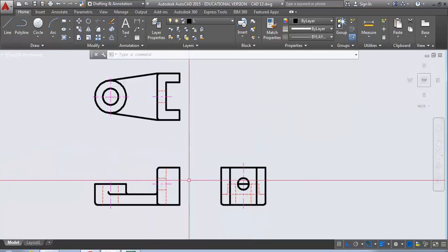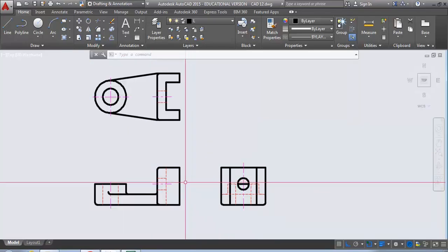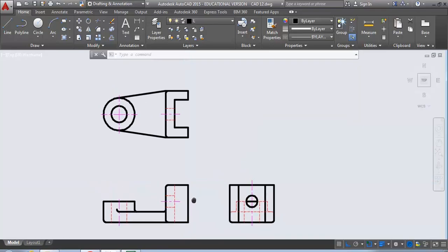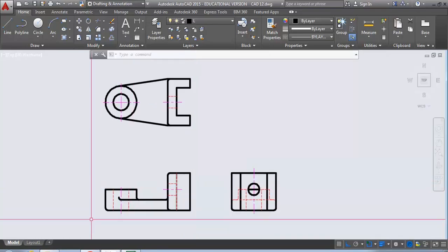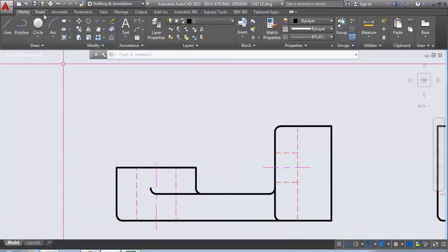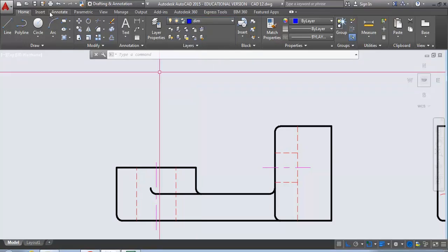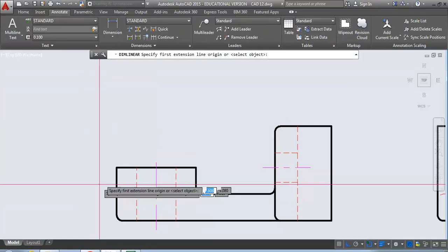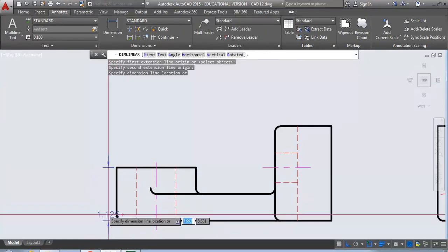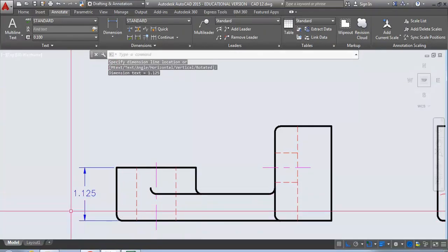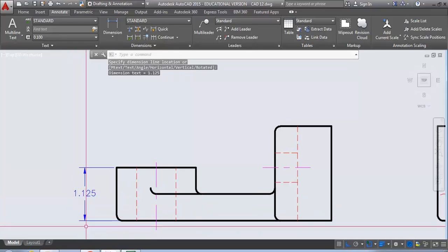Now let's go ahead and dimension it. Again, everything will be 2-place, so you can just copy basically what they got there. Let's set my dimensions to current, either D or dim, either one, doesn't matter. So there, that dimension's right.